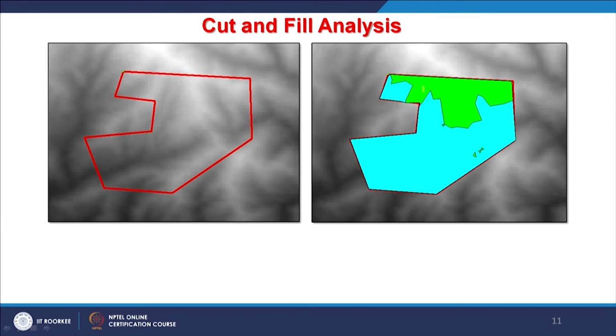which are the areas that will be required for filling and which are the areas that would be required for cutting or removal of the earth or rocks. And by doing iteration, I can achieve a balance or optimization if that choice is available. But if the level is fixed or prefixed, then such things cannot be done.